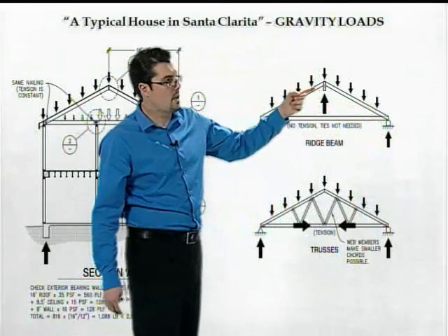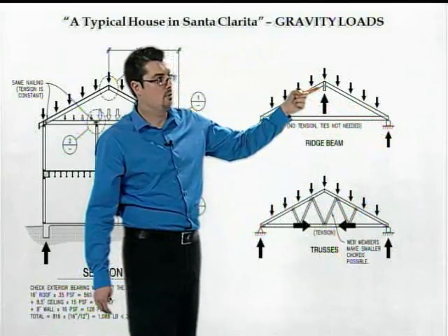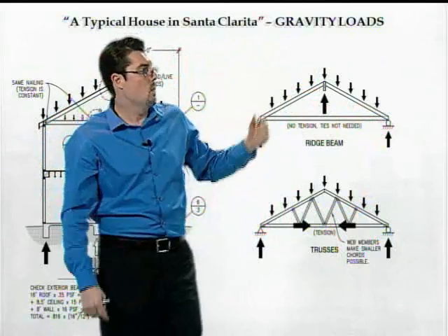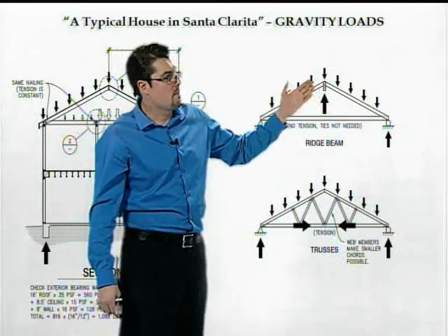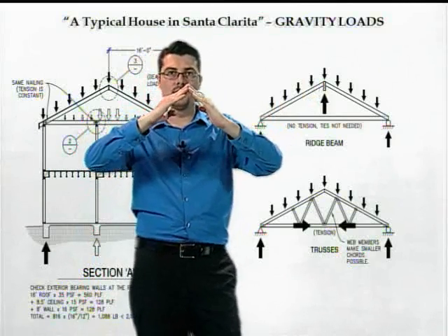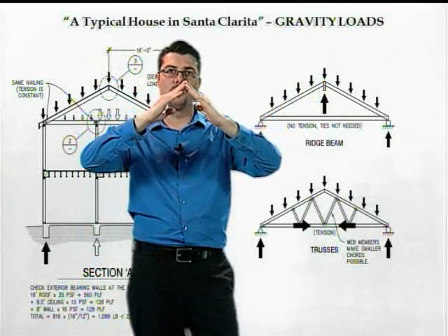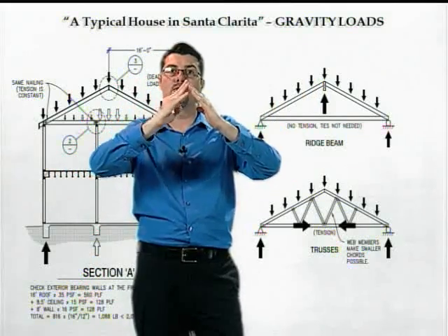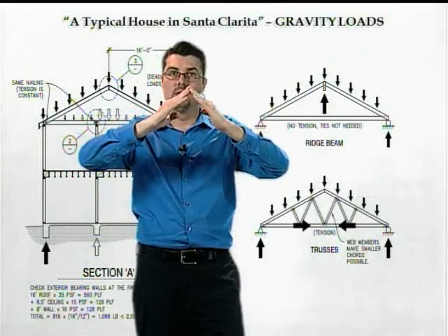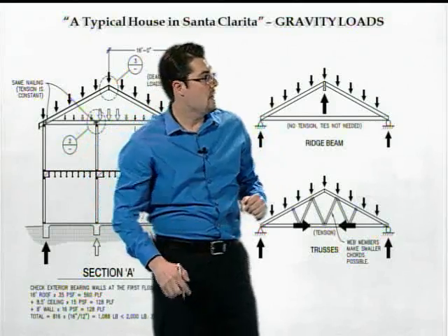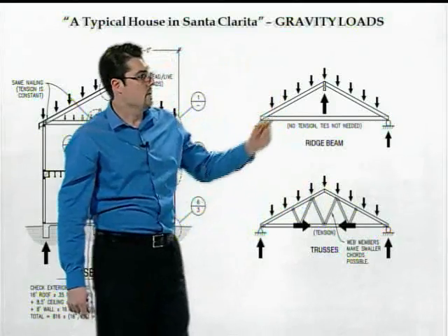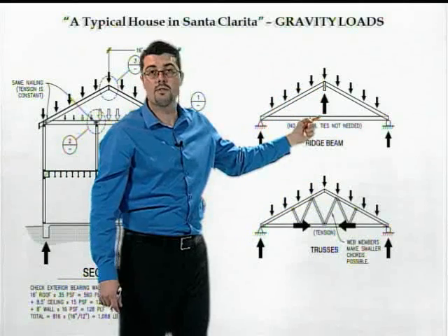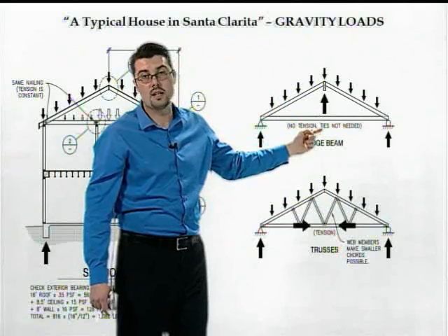You can also put a ridge beam in a roof. Not a board, but actually a heavy structural ridge beam. What that does is, going back to this example, when I try to put vertical load on the roof, it can't deflect or kick down because that beam is supporting it at the center. So that's a stable structure. You can have a structure that has a ridge beam and does not have ties. The ties are really not needed.